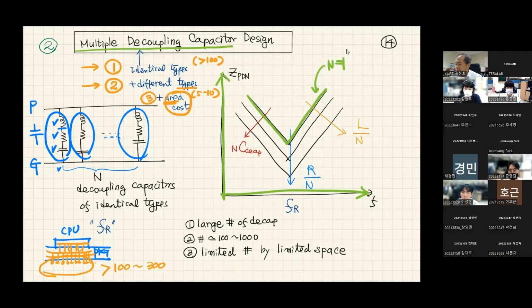Then it has capacitive dominant impedance at low frequencies, at the self-resonant frequency it is dominated by resistance, and at higher frequencies it will be dominated by equivalent series inductance and probably some interconnection inductance.